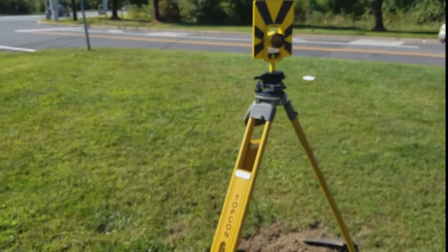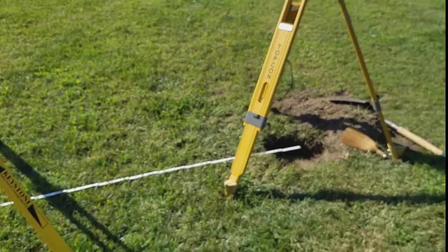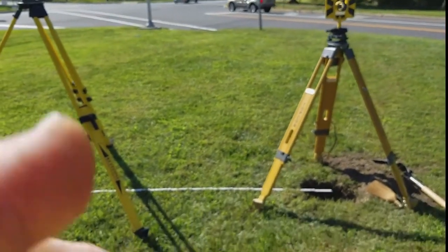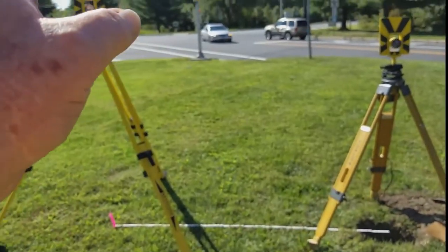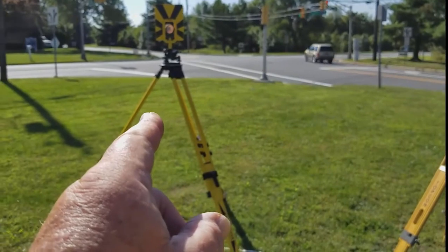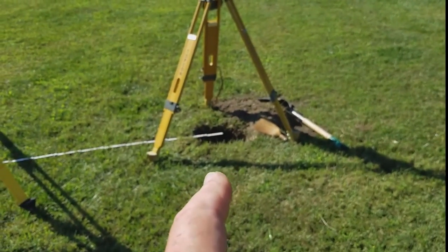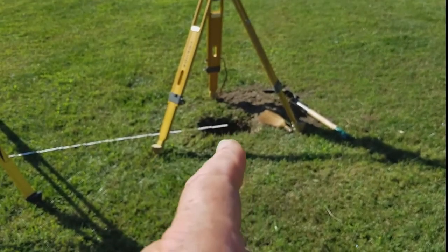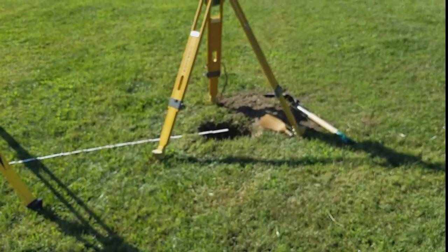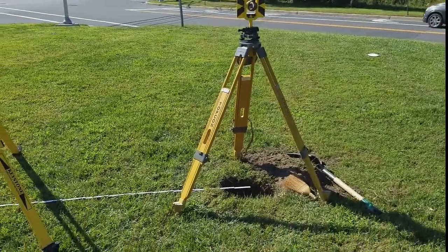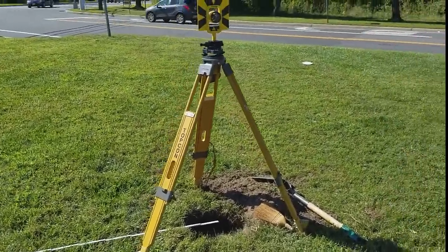With that information and the measurements that I'll make with the theodolite, I'll be able to compute the position of this target over here based on this known set of three-dimensional coordinates: northing, easting, and elevation, or otherwise latitude, longitude, and height. And that's going to be the purpose of the test.